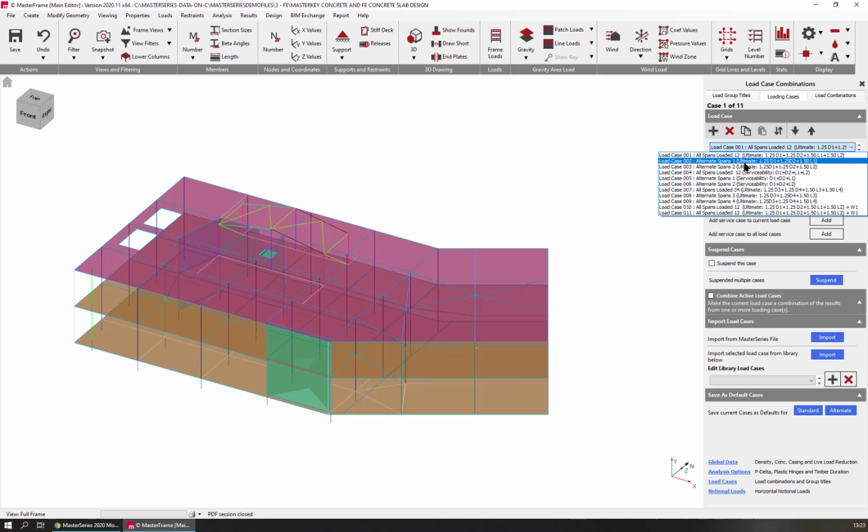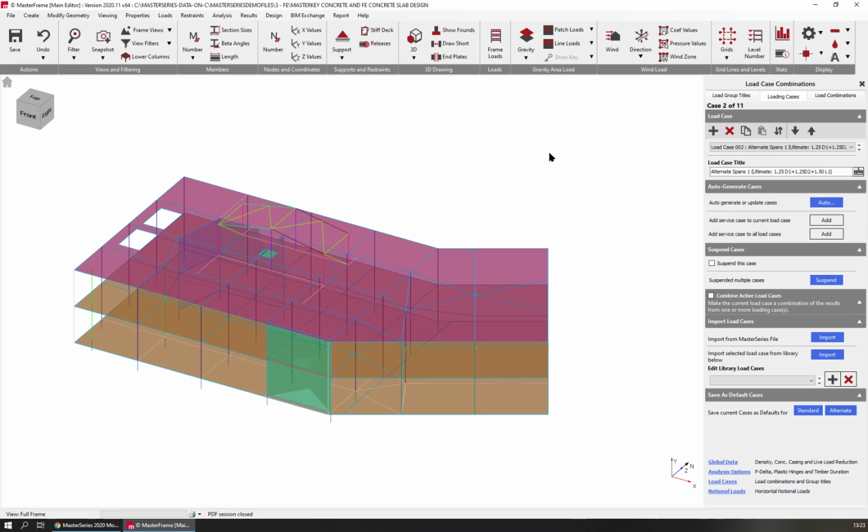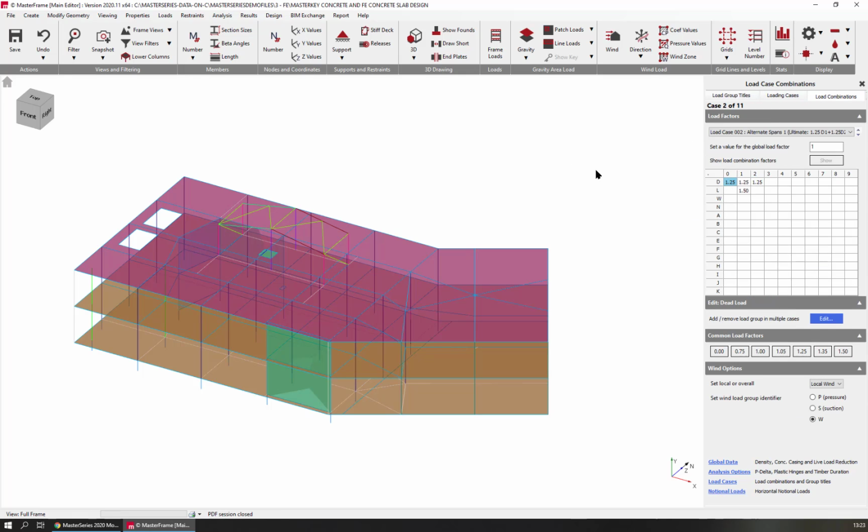So if we take, for example, that one, and look at the loading combination, we're taking our default plus maximum on the D1L1s and minimum on the D2L2s. Now obviously in the Eurocode we don't pattern down the slab self-weights, so we just put the value the same in both cases, and then when you go to pattern 3 you'll see that that's switched around, 1.5, 1.4s. And we have all of those, and I have also put in a few wind loads as well.